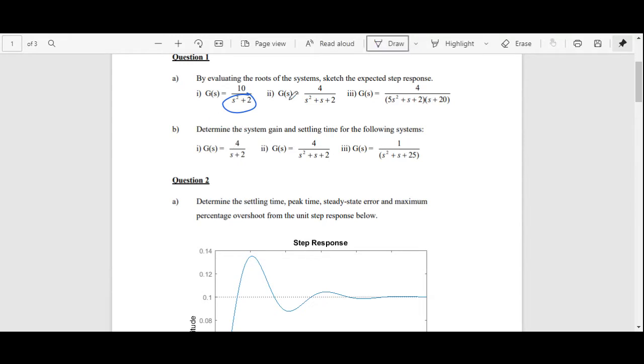Evaluate the poles, and from that, we know the whole rules already in terms of saying if you have poles that are repeated, you're going to have oscillations, but you can have a number of things happening. Let's go back to the fundamental. For a second order system, you can have the system being underdamped, overdamped, critically damped, or in this fourth case, the system will just oscillate with constant amplitude. And the fifth case is where the system is unstable. All right, so those are all the possibilities in terms of the pole location.